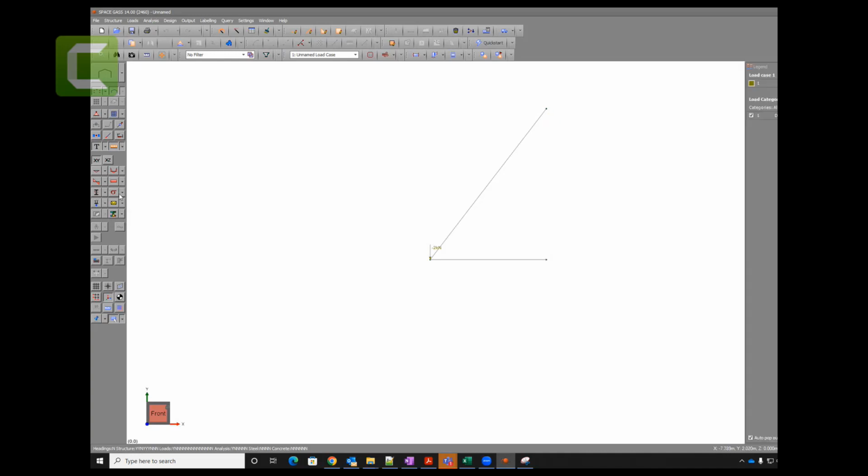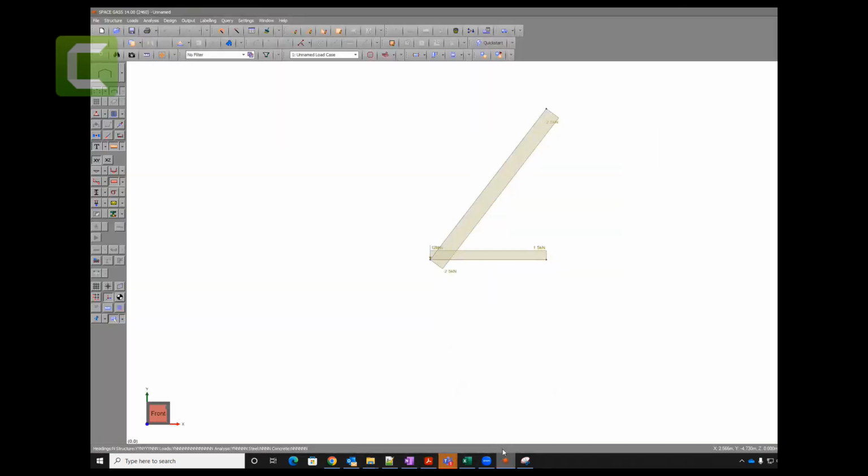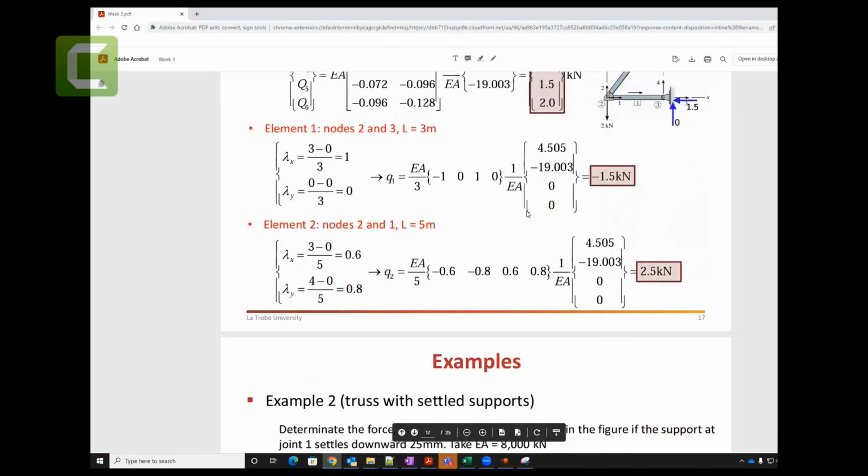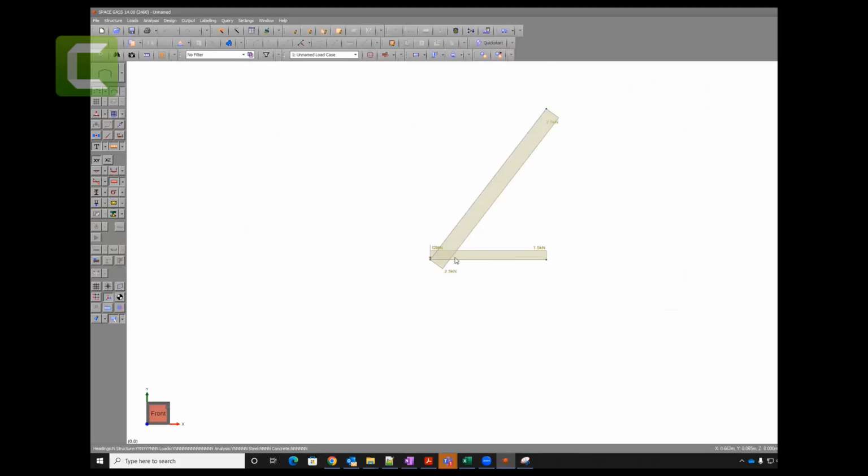Now you want to verify your internal forces. There you go, minus 2.5. Remember, you calculated 2.5 tension force here, and we calculated 1.5 internal forces. You remember that, right? I can show it to you here again, that we did these calculations. You remember Q1 AE over L minus 1.5 compression force. We did it for 1, and that is your compression force.